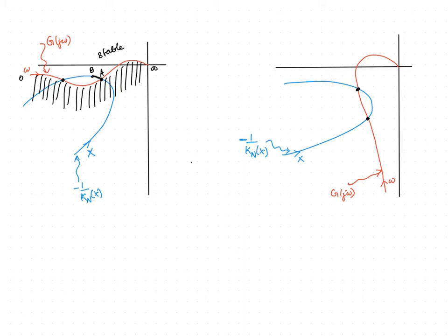Similarly, if the operating point shifts to C, as it lies in the unstable region, the magnitude of the input to the nonlinearity will increase and it moves back to A. Hence, capital A can be thought of as a stable limit cycle because any change in the operating point will bring the system back to A.